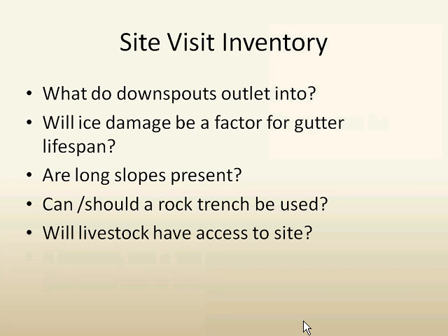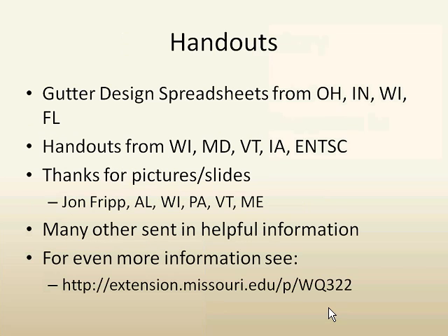What are the downspouts outlet into? Is ice damage a factor for where you're looking at? Is it going to affect gutter lifespan? Are long slopes present? Can I use a rock trench? And will livestock have access to the site? These are all things that you want to make notes about when you're doing your site visit.